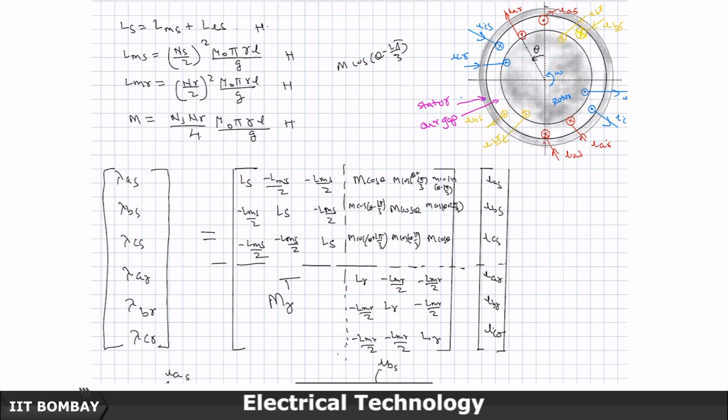This is done. Now, to explain the third term, you can again do the same thing looking at the geometry very step by step, or what you can do is start from the self inductance term and proceed cyclically and write your terms by closing the cycle. So, this was M cos theta in 1 location. Now in 2 location it has become M cos theta. The next subsequent term in the column was M cos theta plus 2 pi by 3. So, I can write here M cos theta plus 2 pi by 3 following the cyclic order, and then the last term will circle back and come here as the first term, which is M cos theta minus 2 pi by 3.